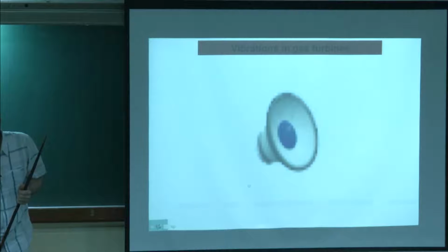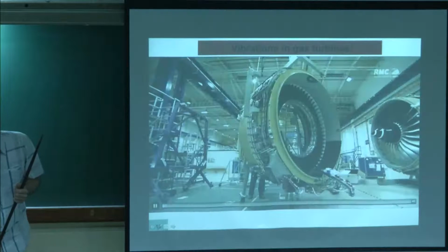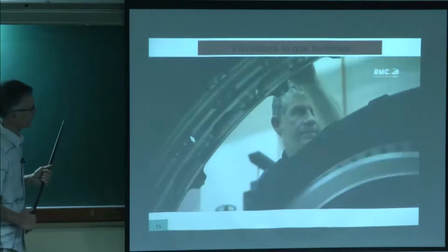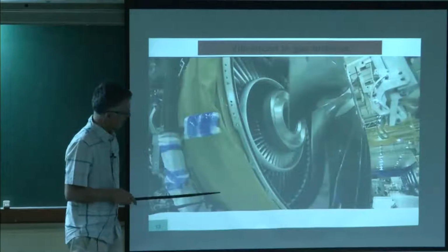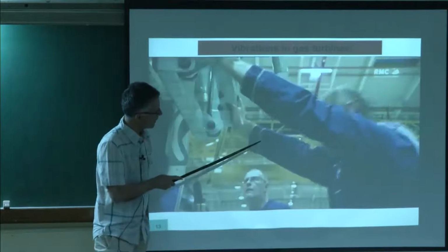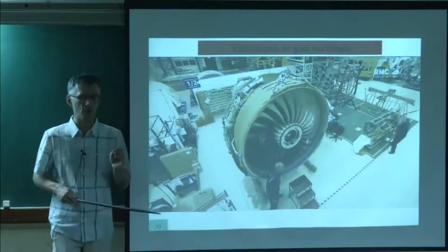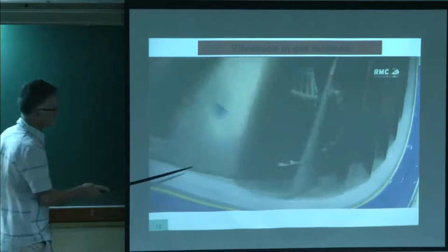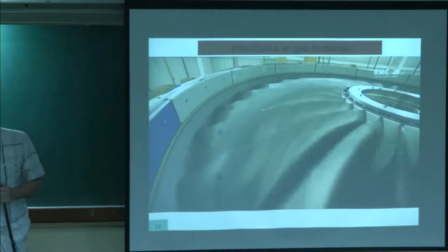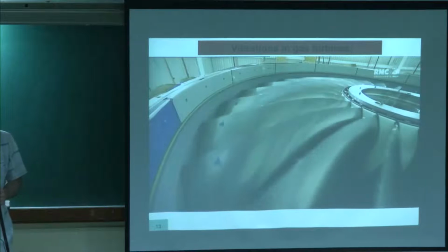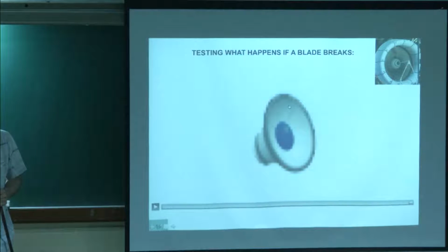In gas turbines, we have the same problem because if something starts vibrating, the turbomachinery parts are very exposed to it. The distances between the blades and the casing, for example, are extremely small. If you start having vibration there and you have a contact between the blade and the casing, then the engine will explode. And you know that when this happens, it's actually a big danger.